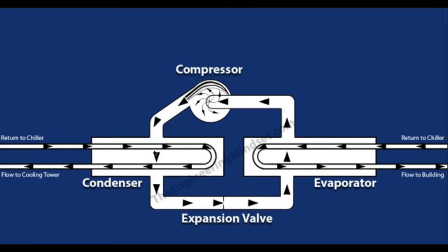That refrigerant enters into the condenser. That dumps the heat into the third circuit there, the condenser circuit, and that is the water which is being returned from the cooling tower up on the roof, and it's entering into the chiller again through these tubes where it's held within. The water in there does not leave. It enters, passes around these tubes, and then leaves again.